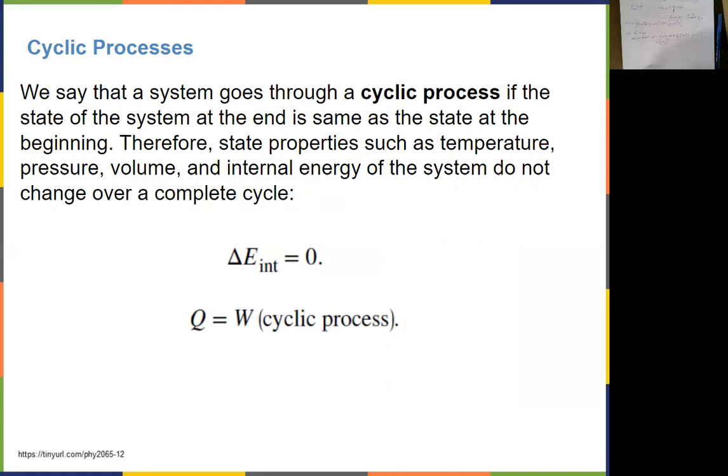In that case, because you are returning to the initial starting point, your internal energy change should be equal to 0. So for the whole process, the work done should be equal to the heat that it receives. That's pretty much how an engine works, like your car engine. It takes heat and it does some work. So the heat difference, that means the heat it takes in minus the heat it dumped out, should be equal to the work done for the whole process.